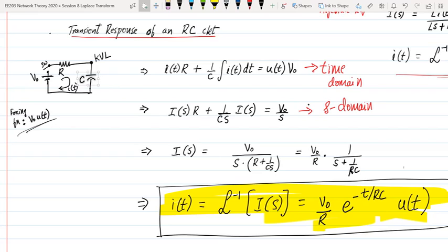And because the voltage across the capacitor increases, what is the current? So let's say that there is some voltage across the capacitor Vc, and there is a forcing function V naught. Then that implies current I is equal to what? V naught is a constant. Vc is a function of time. It's increasing as the capacitor is getting charged. The current then becomes V naught minus Vc by R. Is that correct? Because the current flowing is given by the voltage drop across the resistor divided by R. Simple as that. So I of t is V naught minus Vc by R. And that's what is coming out of this equation over here.